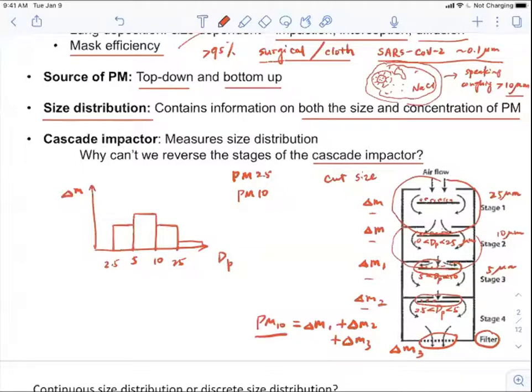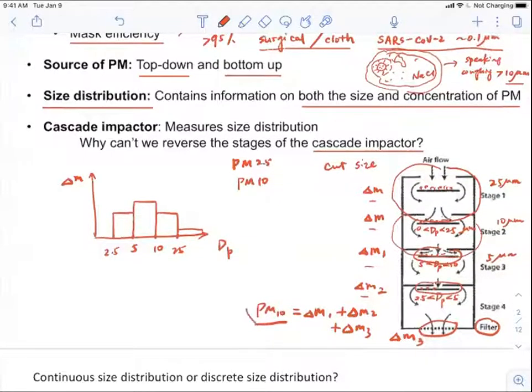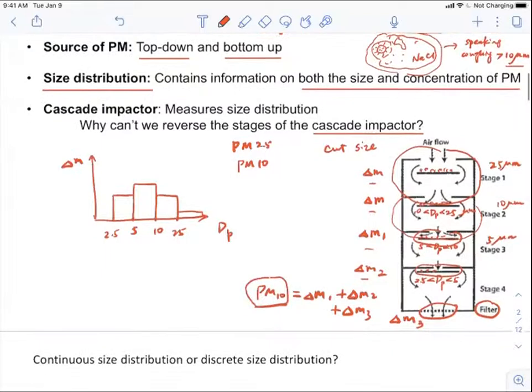So then you may have the question, well, we're just getting an absolute mass. How do we convert that into mass concentration, right? That's also pretty straightforward, because let's say that we have this impactor here and it's operating at a flow rate of 10 liters per minute, right? We can control the flow rate through this device, and we maintain that at 10 liters per minute, okay?